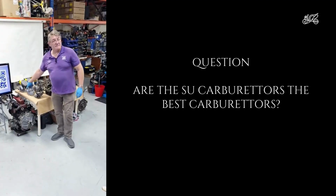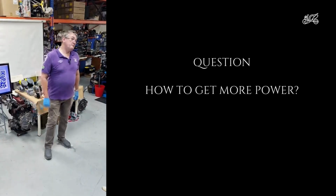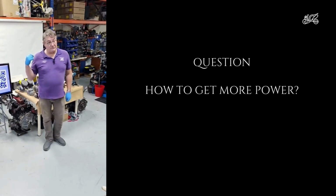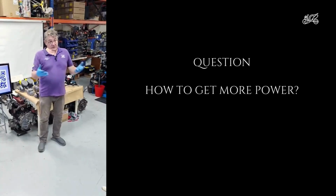Yeah. We've got a question from the chat. Would a fuel injection car run hotter versus a similar carburation car? No, because, going back to what I said about charge cooling, virtually all the injection we've talked about has been port injection. So that charge cooling has been happening.